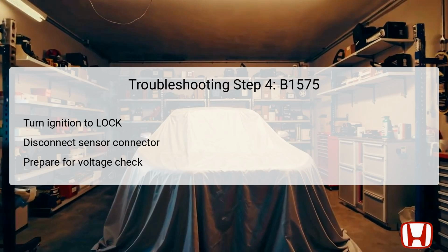Once disconnected, the technician should turn the ignition switch back to the on position, which powers the circuit associated with the auto light sensor. This step sets up for the critical measurement of voltage at the sensor connector, which directly indicates whether the sensor is functioning correctly.